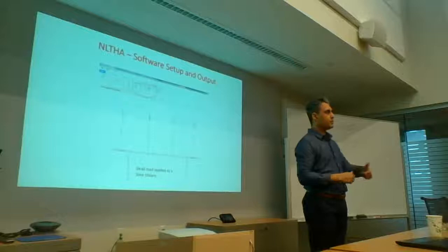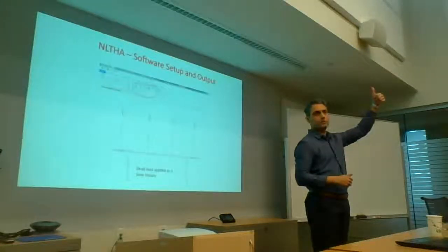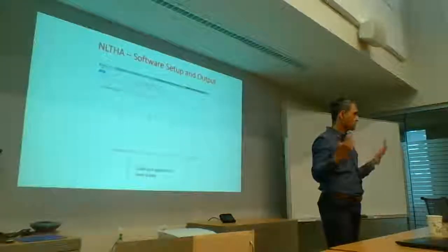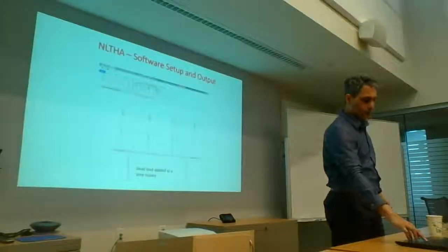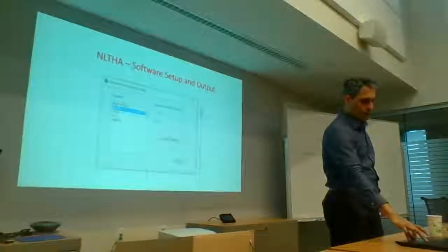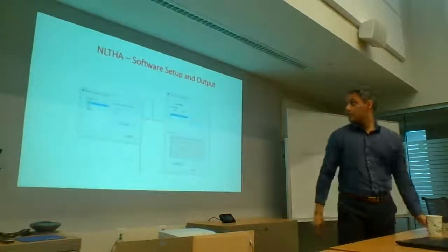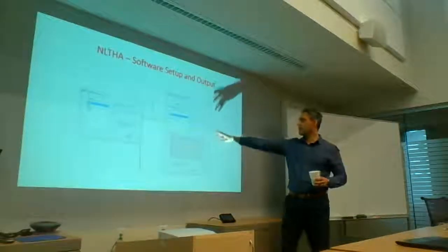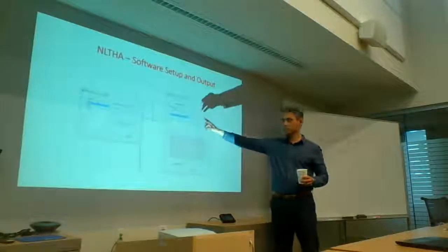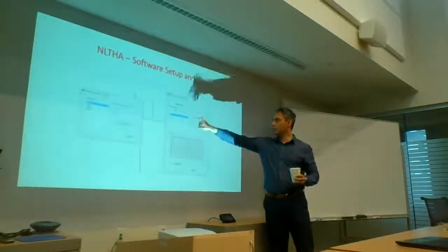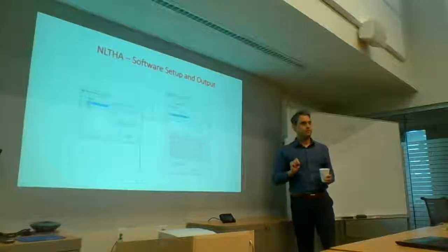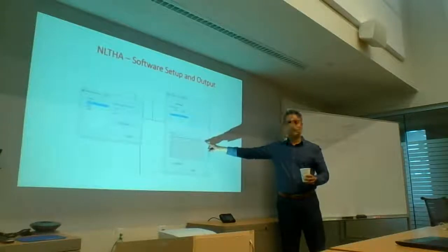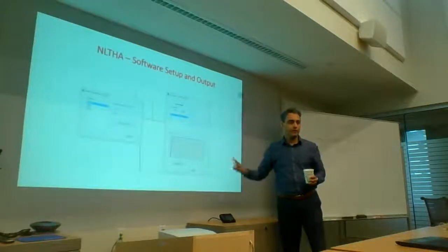So one thought is that you really bump up your damping. You put 90% damping, right? Then it's just going to damp the dynamic response. Okay. Then you have the dead load. So this is the dead load time history. This is how I'm applying it. I take a function. I say the value of the dead load is 0 at time 0, and a full value, 1, at time 1. And then it just stays the same all the way to 20 seconds. It's still 1. Okay? That's how I do it.